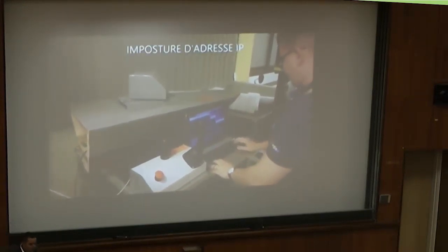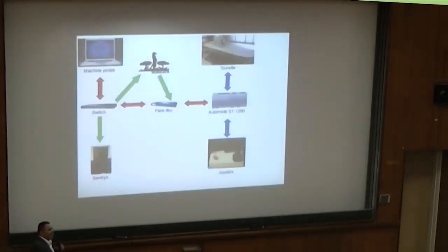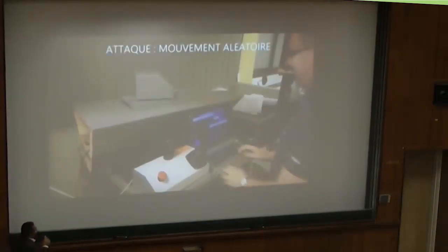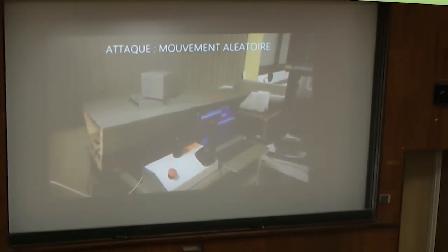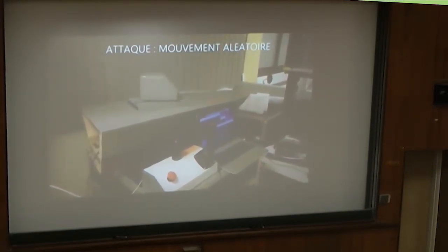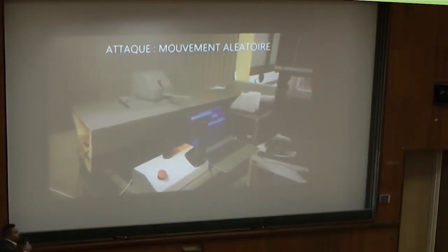Of course, the next step is to hack the firewall to make this attack. At the next step, we put another probe, which is called Suricata. If the firewall can't block the stream, we try to catch all the events, like modifying the password through the PLC, injecting a new block, or something like that.